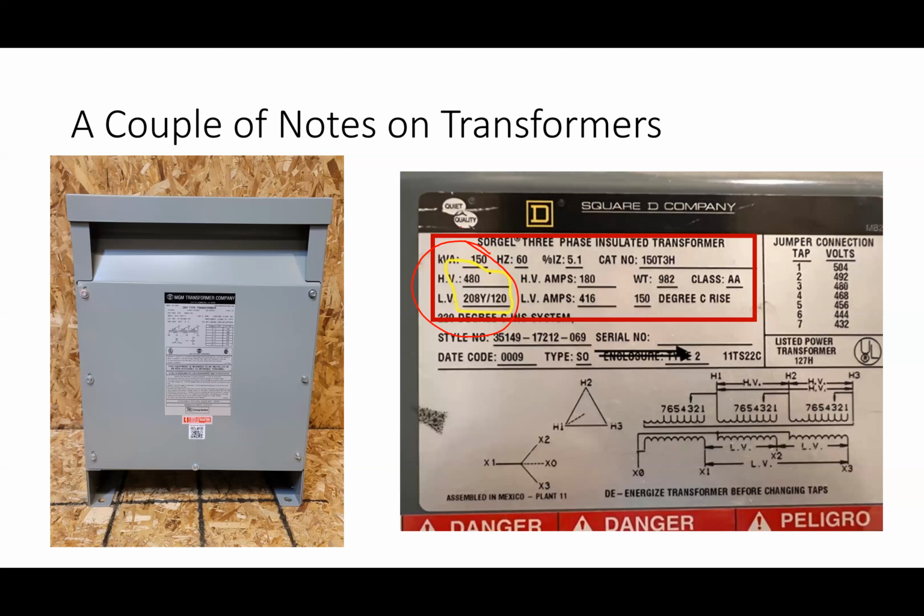So how's 208 and 120? How do I get from 120 to 208? Multiplied by the square root of 3, right? One's a line-to-line voltage, one's a line-to-neutral voltage. Okay. This is specifically, if I'm going into the power grid, so there's a couple of these throughout